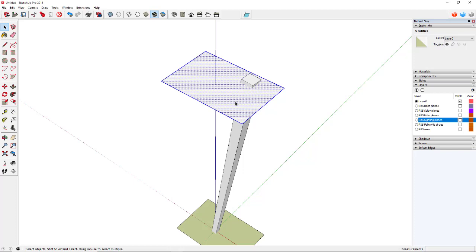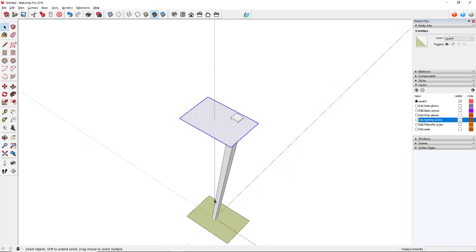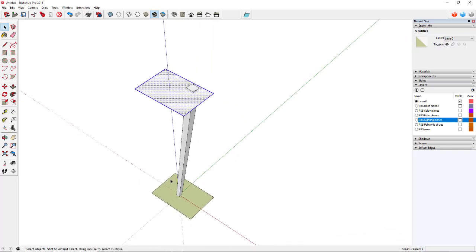These are going to be used as cutting planes, and I've positioned these while I'm outside of the component, but I'm going to put them in the component, and then after running the intersect faces operation that's coming, when I delete things, a little bit of each of these faces will form the new ends for the leg.